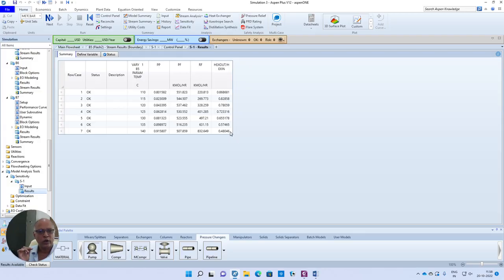So there are some advantages, there are some disadvantages. On one side, increasing the temperature is improving the purity, but the penalty is that it is going to increase your recycle flow rate, it is also going to decrease the product flow, and the recovery is quite small. Unnecessarily, if you are recovering about 48%, 52% of the product is finding its place into the recycle. Unfortunately, this is going to increase the size of the equipment, right? So this is how you will be in a position to vary the sensitivity.